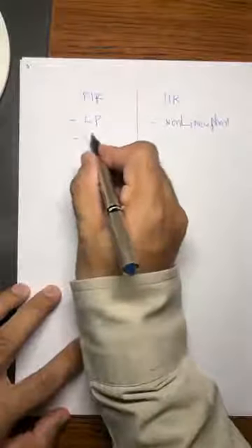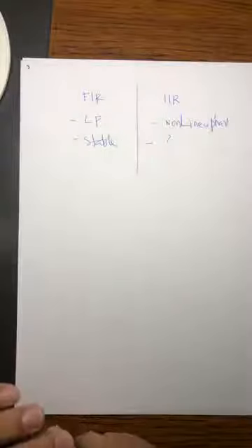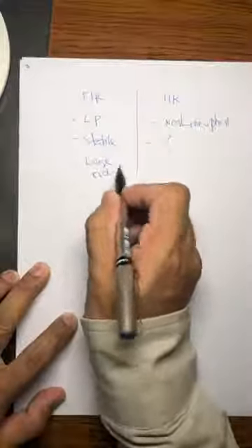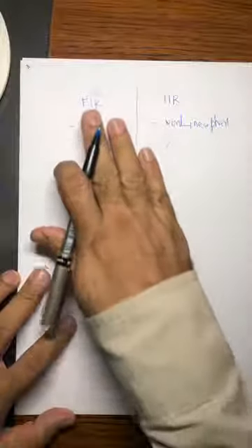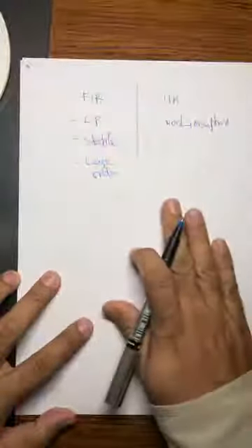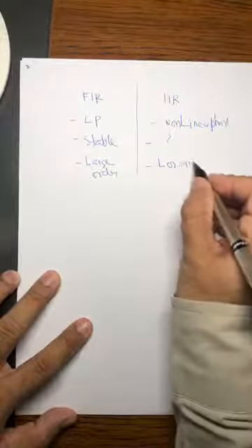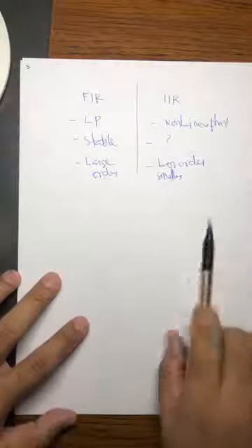This is always stable, so you don't need to worry about its stability. This one, you need to worry about its stability. All the poles must be inside the unit circle. It has usually large order, so this is a compromise. Whether you want more computation, but you don't want to worry about stability or the phase, or you want less computation. Usually these are smaller order. It's up to you whether you want to do this or this.